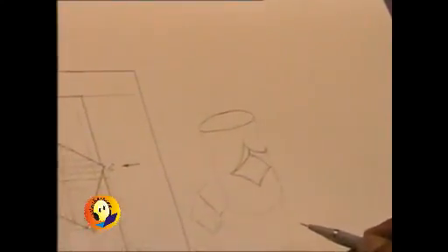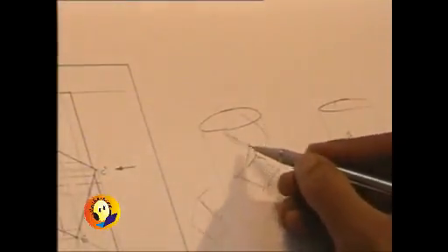This is how it will appear once you cut it. It is a cylinder which has been cut through. You can also imagine that if this square hole would have been cutting the center, then it would have appeared this way. This is easy to imagine. This is how it will be seen when it is cut. This is actually the sections of the cylinder through the cutting planes, like the one I am showing over here. This is one section, so this portion is removed.